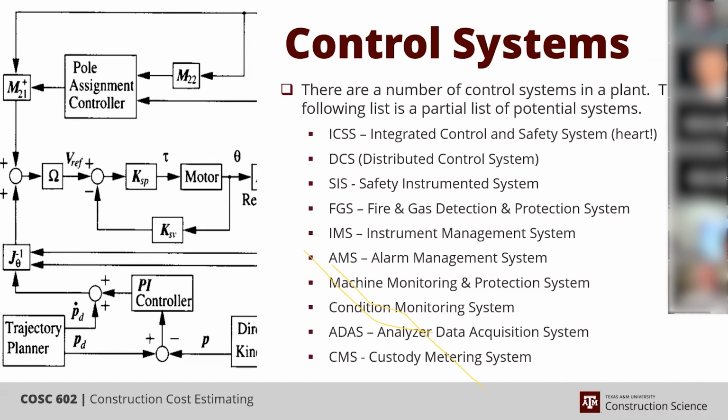Some of these programs maintain and drive the whole system, while others are focused on specific activities like fire and gas, managing alarms, or monitoring the equipment. If one system says we've got a problem, it will interface with another. Fire and gas will interface with the AMS, and the AMS will then tell the alarms what to do, but the fire and gas is what detected it and said we need to do something.